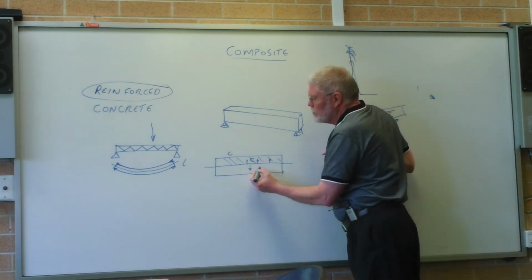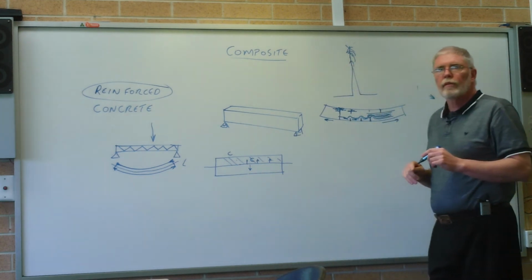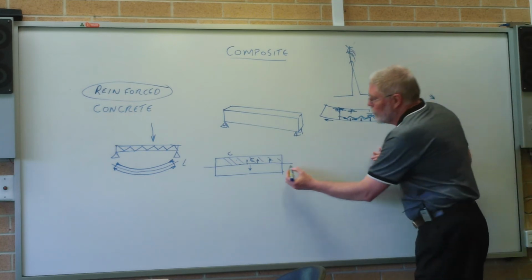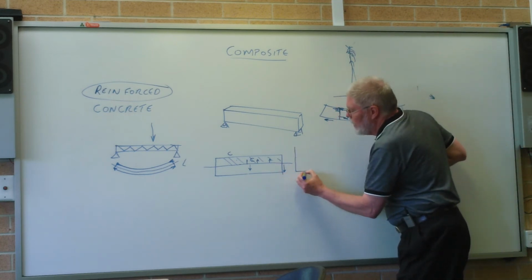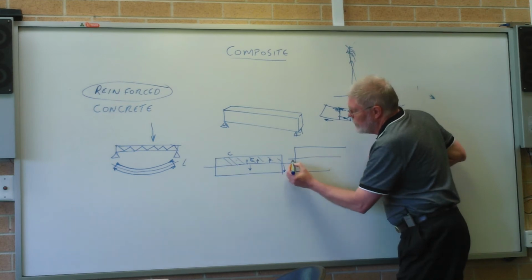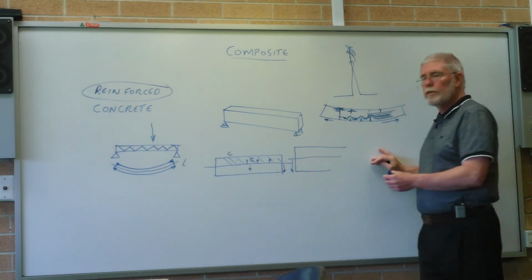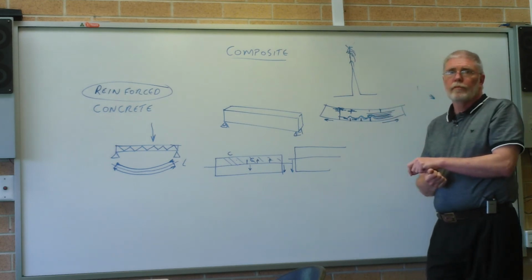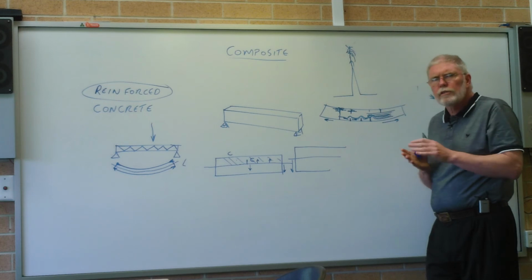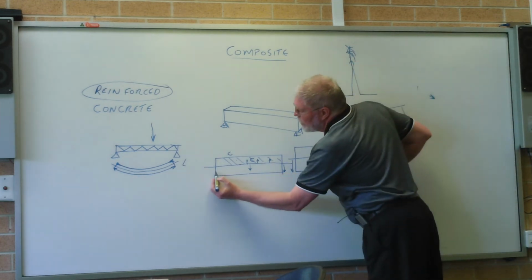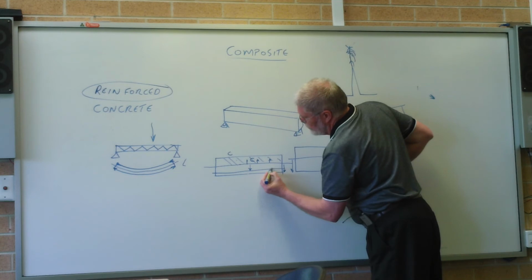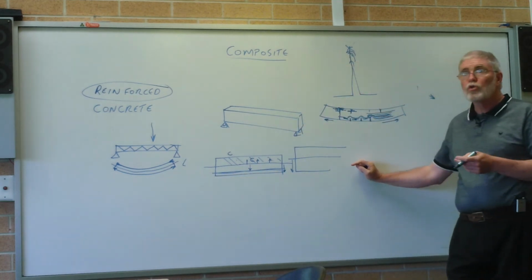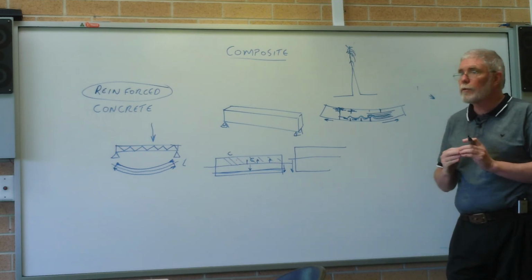Below that neutral axis, we increase our tension. Where is the most tension? At the bottom, the furthest away. And if we make the beam larger, then that distance is further, which means the tension is higher at the bottom if you deepen your beam. So now we have to think through, where will we put our steel? We want our steel to be in a place towards the bottom where the tension is at its most, so we can keep the thing from cracking open.